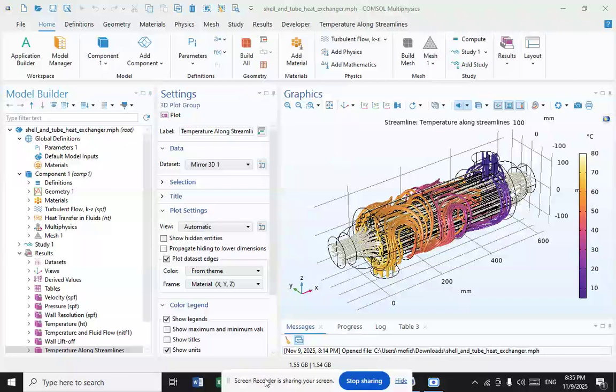Having baffles spaced too closely causes a greater pressure drop because of fluid redirection. Conversely, having the baffles spaced too far apart means that there may be cooler spots in the corners between baffles. It is also important to ensure the baffles are spaced close enough that the tubes don't sag.